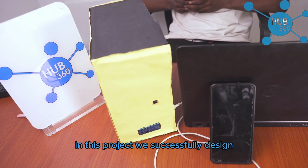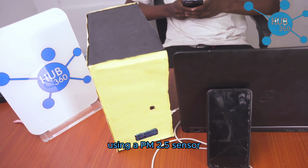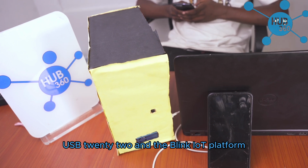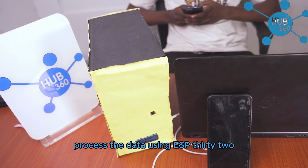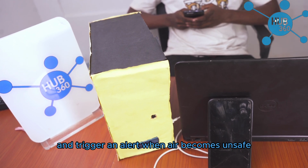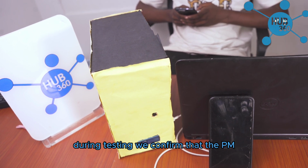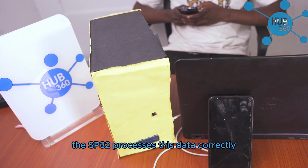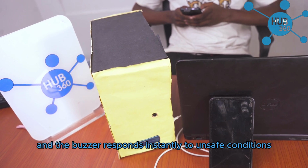In this project, we successfully designed and built a smart air quality monitoring system using a PM2.5 sensor, ESP32, and the Blynk IoT platform. We were able to measure real-time air pollution levels, process the data using ESP32, send it to the cloud, display it on a mobile dashboard, and trigger an alert when air becomes unsafe. During testing, we confirmed that the PM2.5 sensor provides real-time data, the ESP32 processes this data correctly, and the buzzer responds instantly to unsafe conditions.